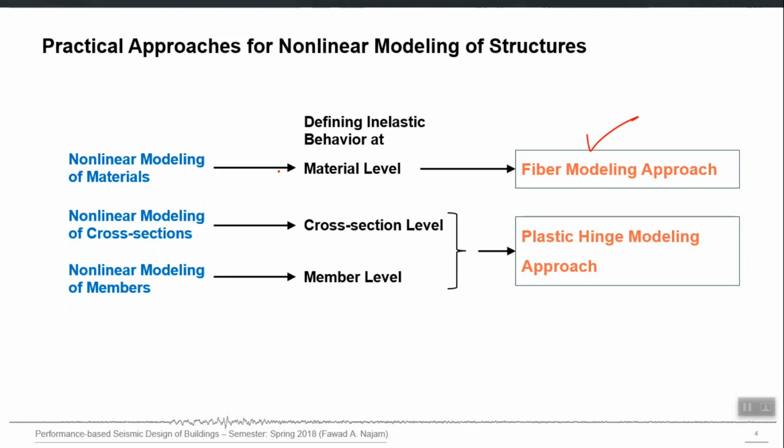Here there will be some physical length of the element which you will define, for which you will use nonlinear materials, and then in between two of these segments you may assume the material to remain linear, right? So that will actually be the lumped fiber approach. The fiber approach is actually a distributed plasticity approach, but it can run along the whole length of the element or at a certain segment which you may define.